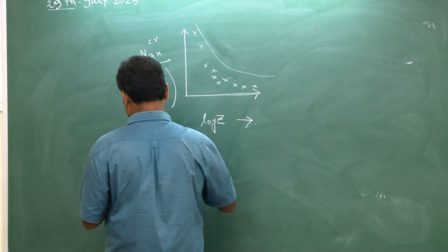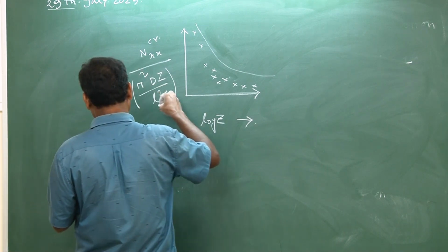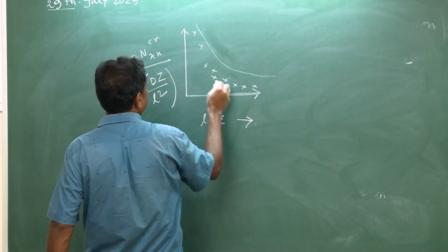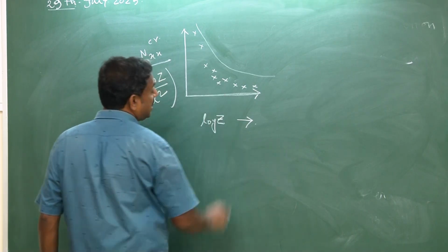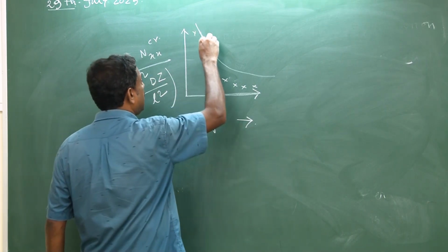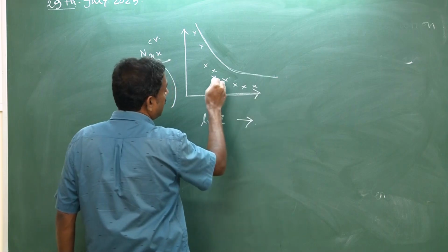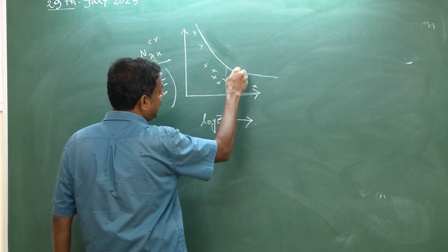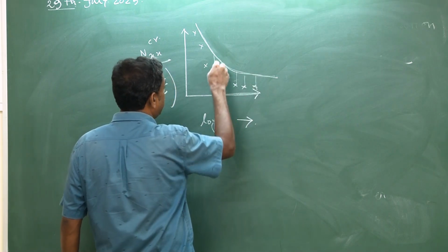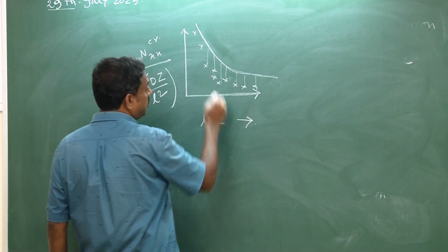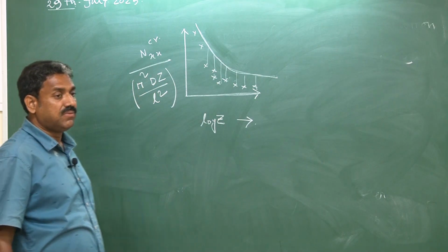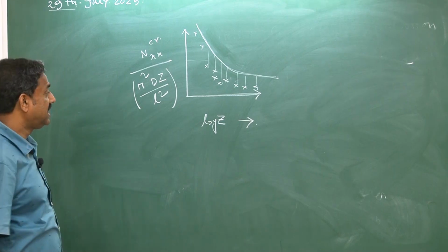Here it is logarithmic. So, you see from here there will be a huge drop. Whatever this critical load is, some kind of upper bound it is forming, but there is a significant drop in this load. Why is this drop happening? Because all these closely spaced modes conspire through modal interactions, and they reduce the load.